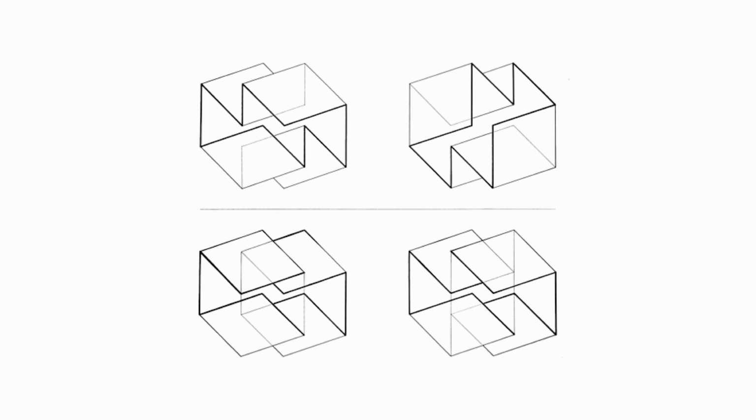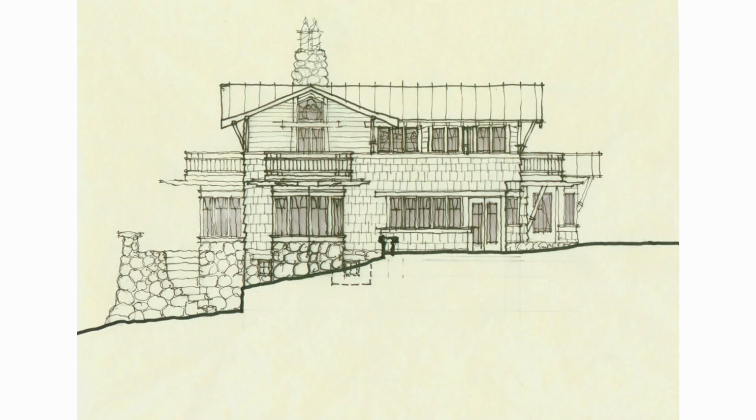So here's an example of the same drawing 4 times, and depending on which lines are bold, certain pieces stand out or go back. And so as you look at this, even though it's the same drawing, these look like different objects, just based on the line weight itself. So let's talk specifically about elevation views, and how do we work with line weights in an elevation view. So we know that the thickest line is the part that you cut through.